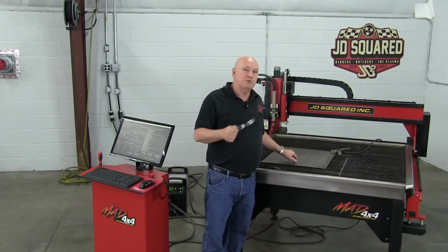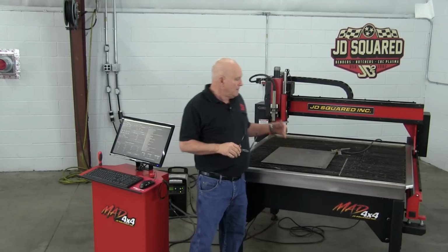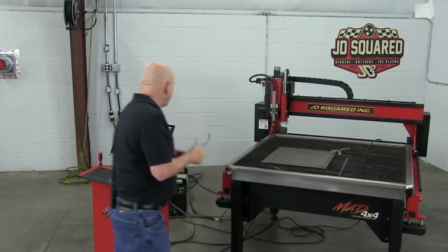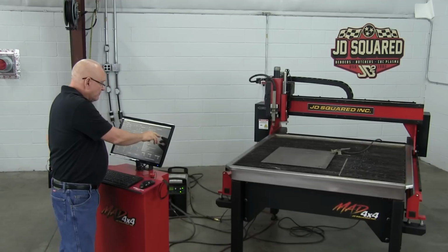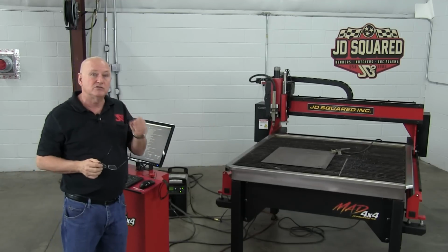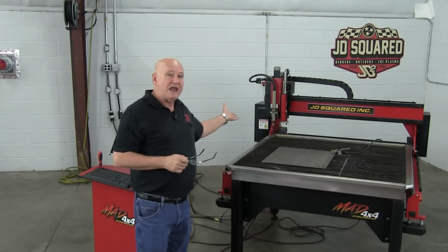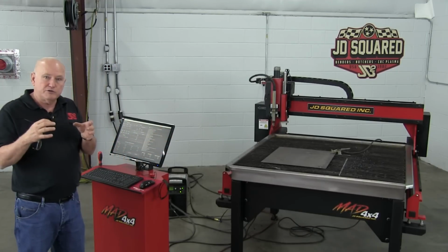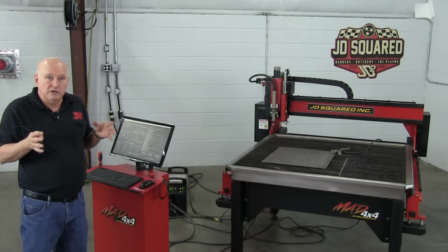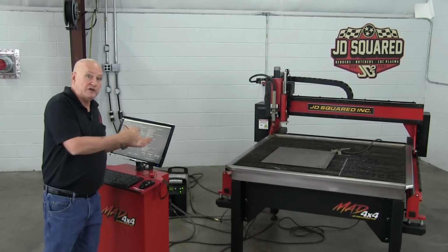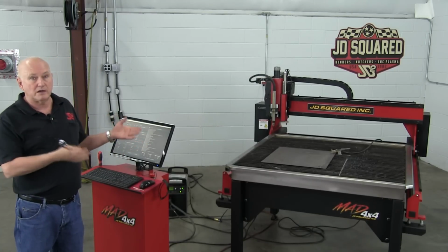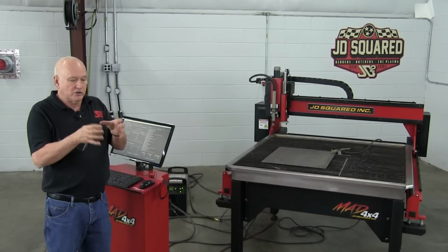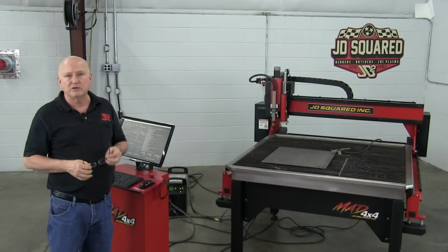So if you generated a program in SheetCam, say, and you said, hey, I'm using 85 amp consumables, it's going to look, for instance, and say that the kerf width is 49 thousandths of an inch wide. Well, let's say we load up 85 amp consumables in the machine and we hit the go button and it cuts out your part, and it's probably not going to be a good cut, but let's just say you did, because remember the speed and feeds and the voltage for tracking were also set in SheetCam or another CAM program. So it's going to cut out bad, and you're going to measure and you go, wow, this doggone part's undersized.